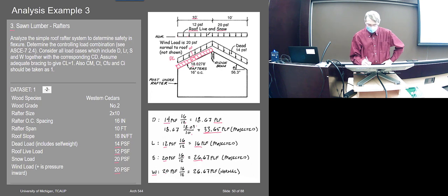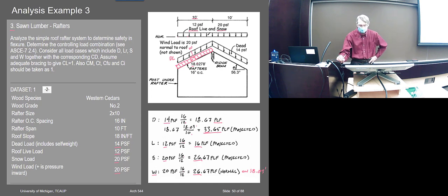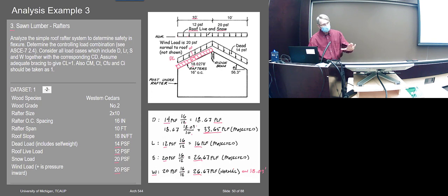I'm not calculating the moment yet. First, just to get that on the rafters, I convert that by 16/12. So that would be 26, but it's 26 on the full length, on 18.03 feet, not the projected length. Okay, so now I've got all those.